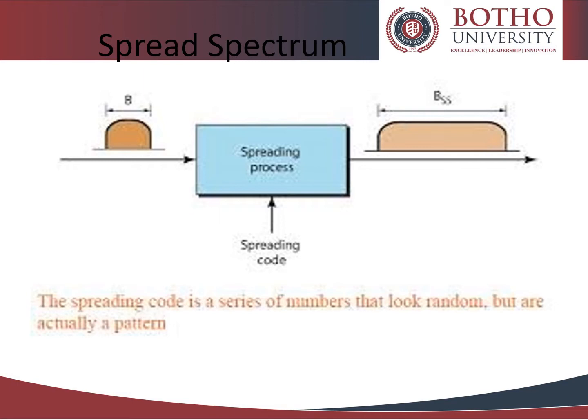The first two of these, that is FHSS and DSSS, employ pseudo-random number sequences created using pseudo-random number generators to determine and control the spreading pattern of the signal across the allocated bandwidth. The standard IEEE 802.11 uses either FHSS or DSSS in its radio interface.